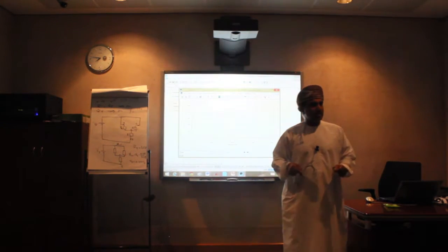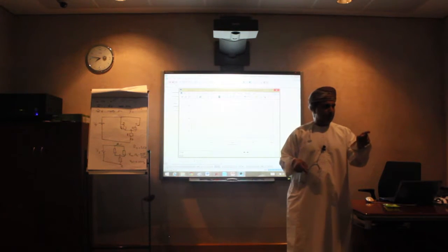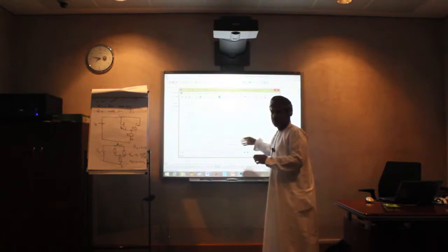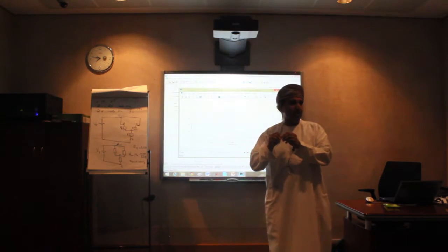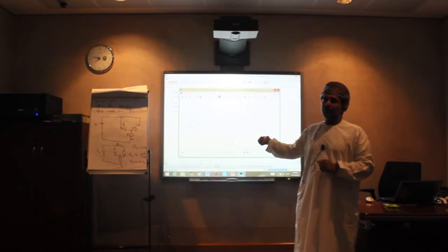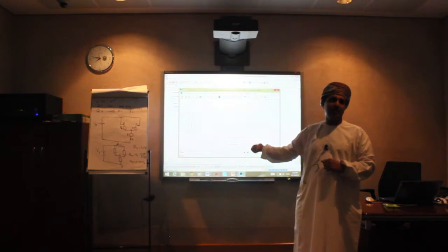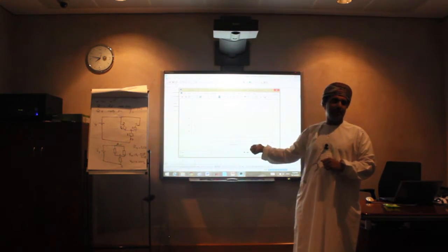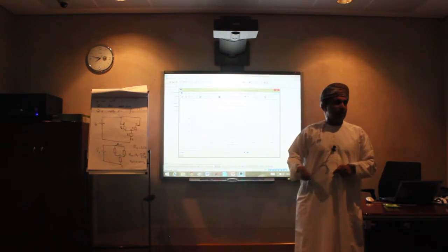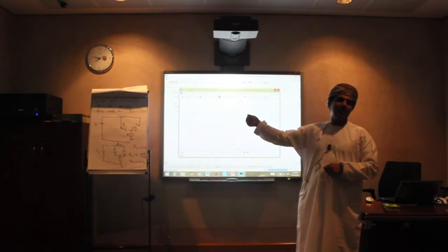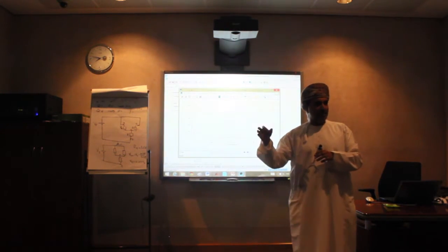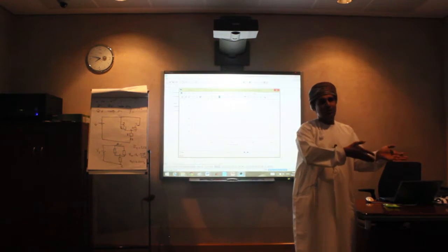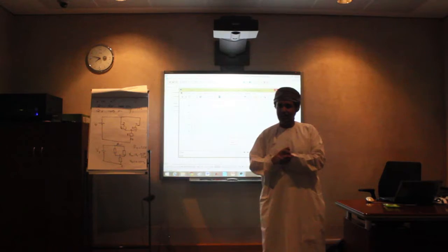But you might ask me, why VFD, while 6 pulse has those harmonics? Why don't they use pulse width modulation with high frequency so they can design a small filter? This one also, in the drive, has another problem which is known as reflected wave. It can cause a reflected wave, and it might damage even the inverter itself, if it is connected, for example, to a long cable like in a well for oil production. But the other one, because it has only 6 pulses, a reflected wave will not appear that much compared to that one. That's why they prefer to go to 6 pulse than to go to that type of inverters.